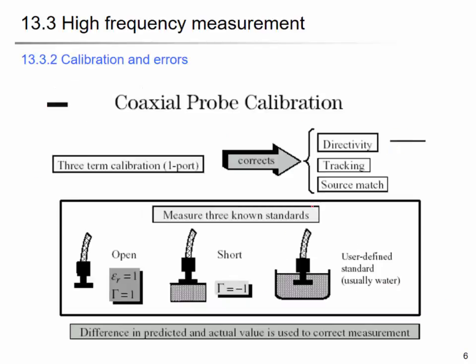So then how can we calibrate? It's the same as what we did for the low frequency measurement. Do you remember how we did it? We did the short circuit measurement and the open circuit measurement. From there we extract the value of L, the inductance of the cable, and the resistance of the cable, right? So it's the same.